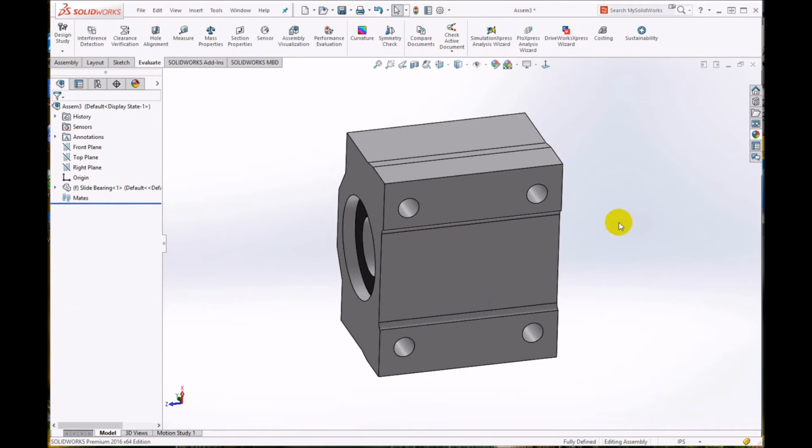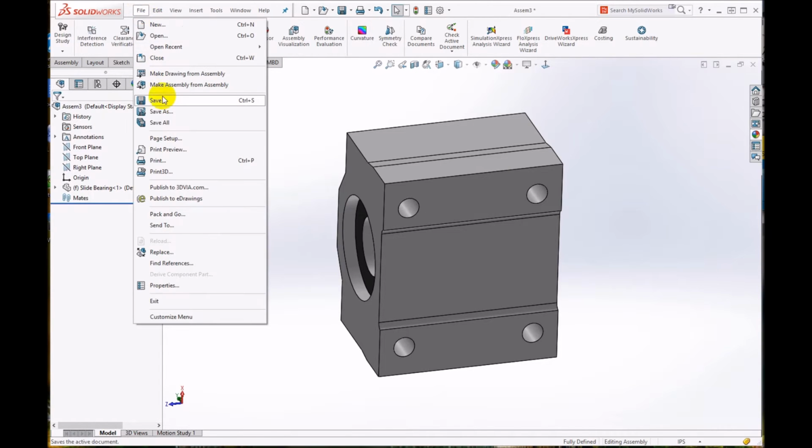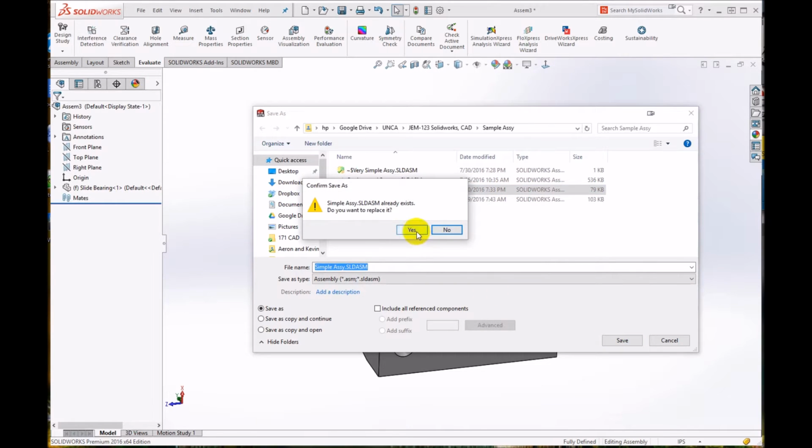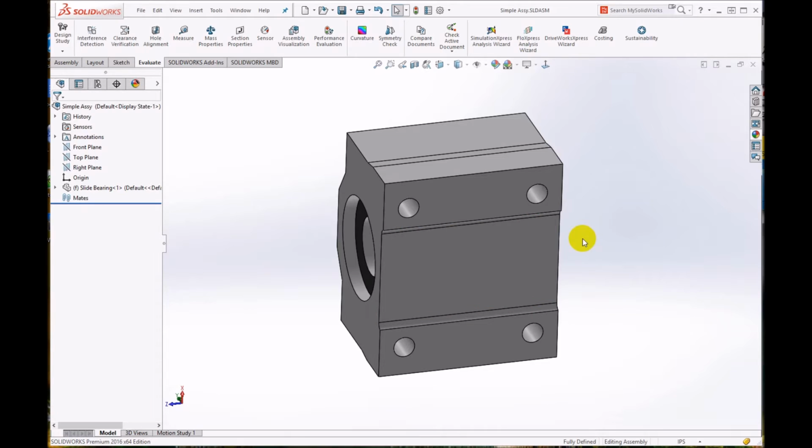Okay, there we are. Before proceeding any further, and you'll remember this, either you remember it the easy way or the hard way, I've done both. You want to save the assembly such that it is guaranteed not to change names later. Here I'm overwriting one, but I've created a simple assembly. The reason for that is that when you create a new part that's based on an existing part, much of the context is contained within that assembly file.